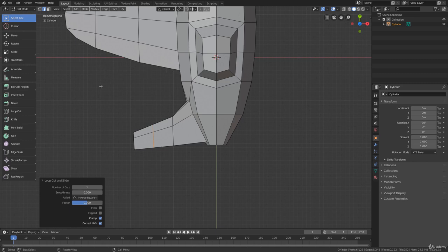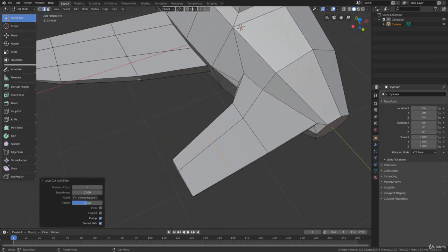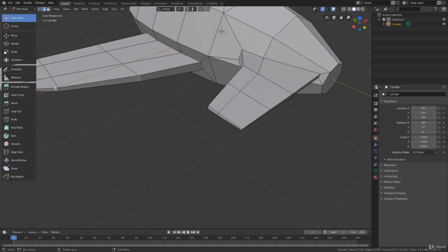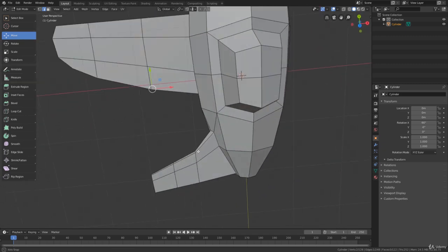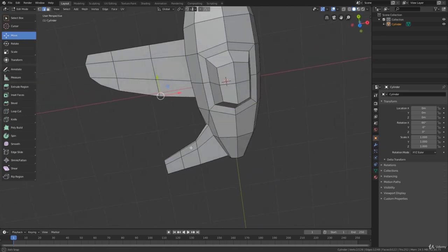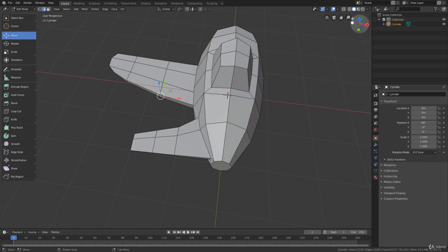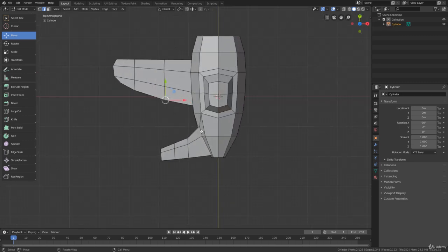And we can do as we did in the front wing, that we select these vertical edges, and with the move tool we move them back and forward to adjust the shape. Or we can make this adjustment by using the vertex selection mode.